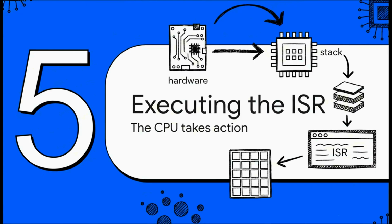So the NVIC has made its decision. It gives the CPU the green light. At this point, everything is automatic. The hardware freezes whatever it was doing, saves all its important registers onto the stack, and then it looks up an address in a special list called the vector table. That address points directly to your code, the C function you wrote to handle the event, also known as the interrupt service routine, or ISR.